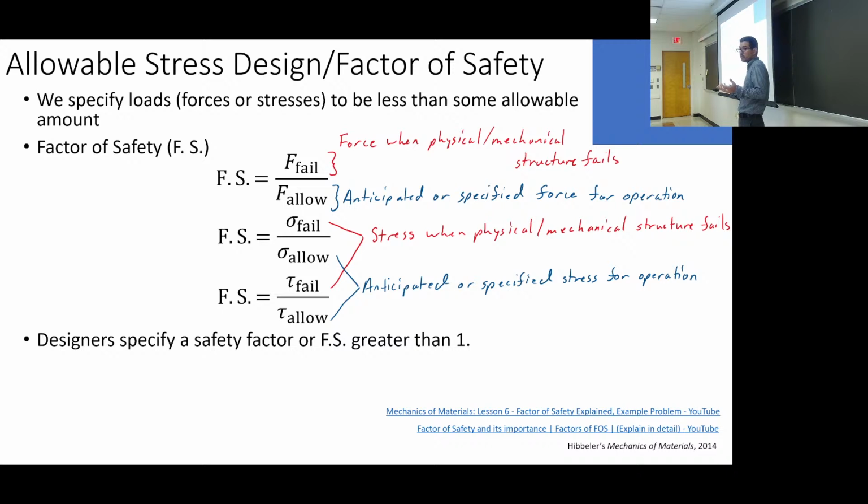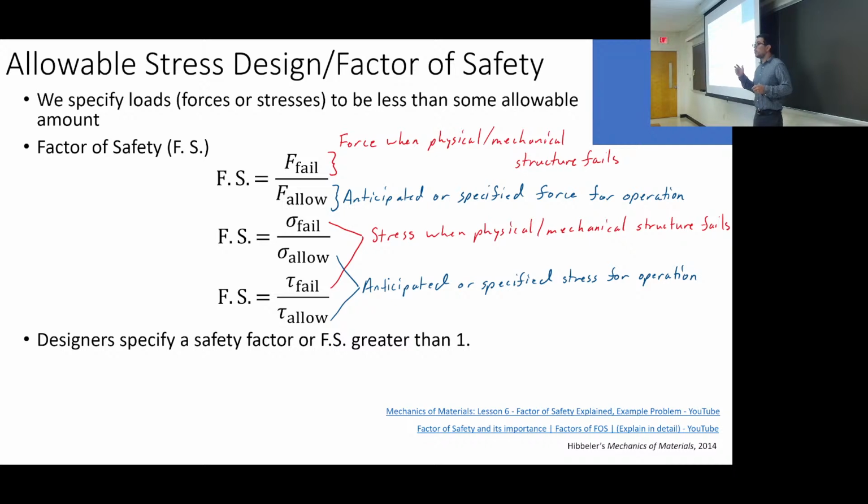For example, with a cylindrical pressure vessel, I have a sigma 1 and a sigma 2, and I have a pressure inside. So I crank up the pressure, sigma 1 and sigma 2 both increase by the same factor, and I have to think, okay, I multiply that pressure by this factor, and then I get maybe a maximum shear stress, because pressure vessels are often made out of ductile metals.